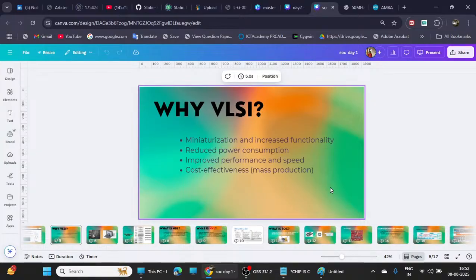Yeah, APB. So what is APB? APB is an on-chip protocol, Advanced Peripheral Bus, given by AMBA. It comes under the AMBA protocol and is for interfacing peripheral devices to the chip. For example, if you are working with some sensor, between the chip and the sensor we use an off-chip protocol like UART or I2C.